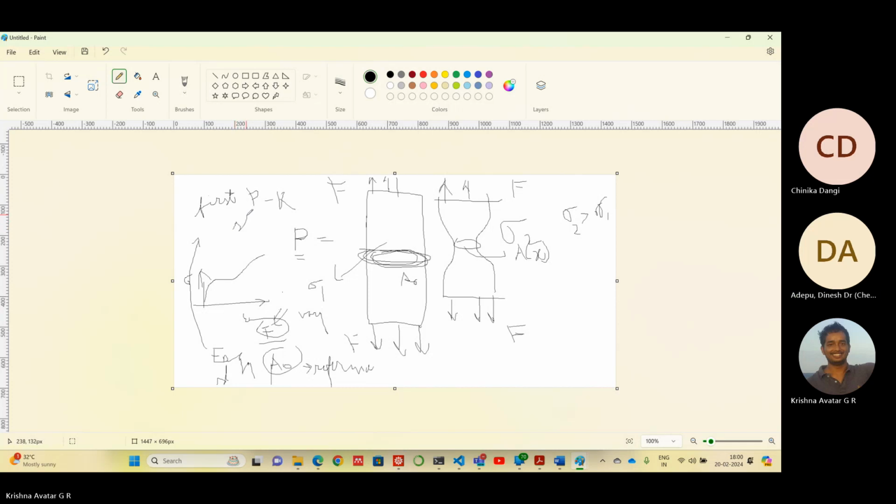So now we understood the idea behind P. What P does is it actually takes both the configurations into account. It uses the area from the reference configuration and the force from the current configuration. So now you realize that P will have indices, say small i and capital I. Capital I denotes the index defined in the reference configuration, and small i denotes that we are also dealing with traction.